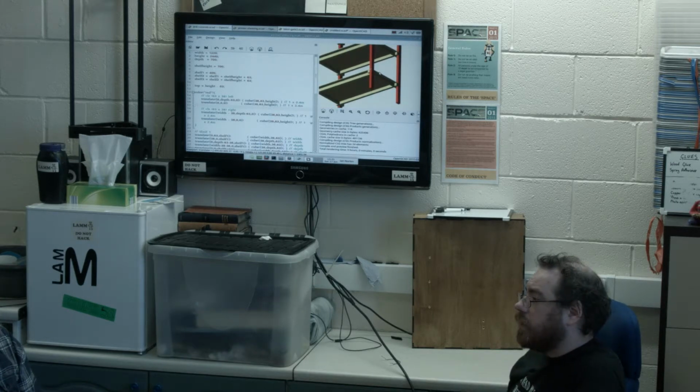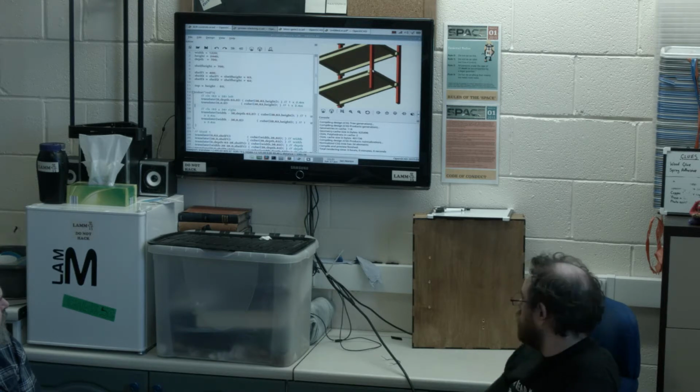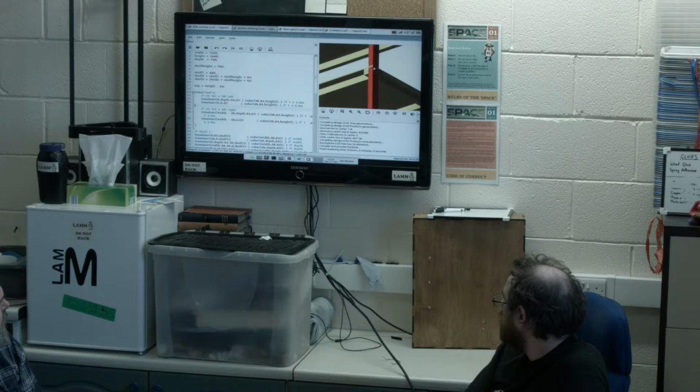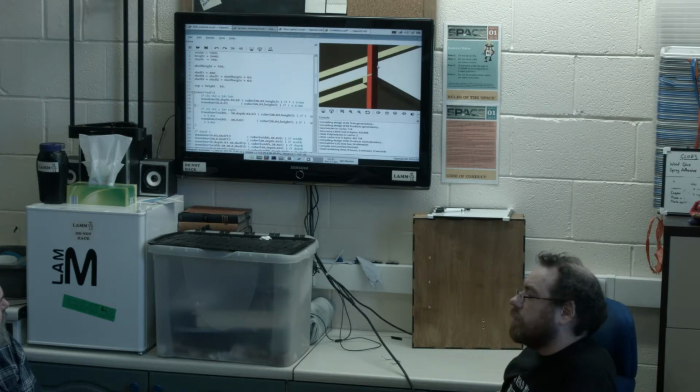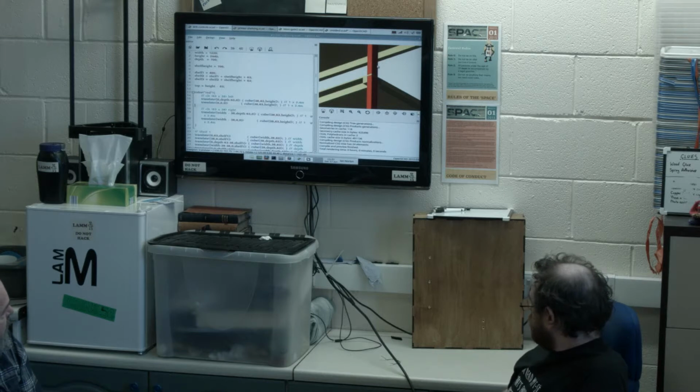So you were asking what union and intersection are for. You can see where you've got the intersection of the parts. If you scroll right in, you can see it. If you used union, that would make those two one piece. If you used intersection, it would leave just the bit that overlaps.